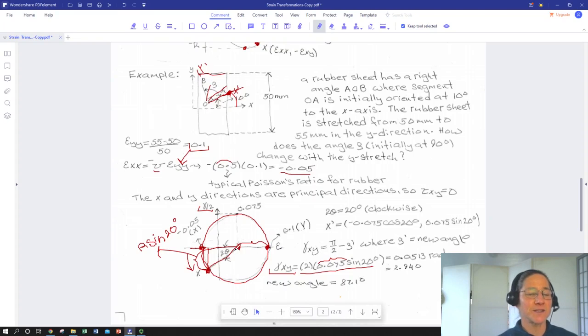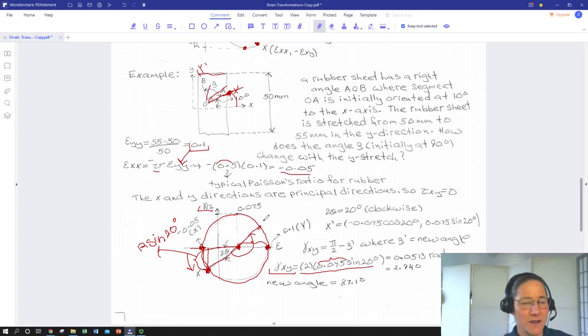And you'll notice if we said, well, why couldn't we get that corresponding shear at y prime? It would give you the same shear, because if you look at where y prime is, it's 180 degrees, again, counterclockwise from x prime, so y prime's over here, and this angle is the same as that angle, and the radius is the same.